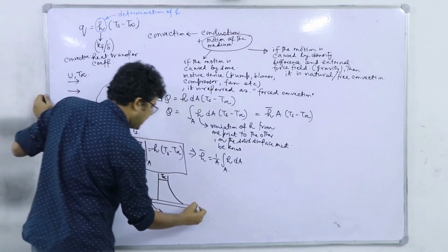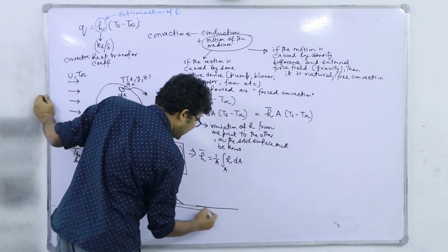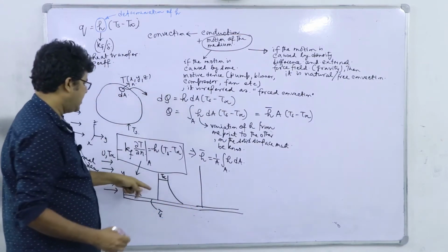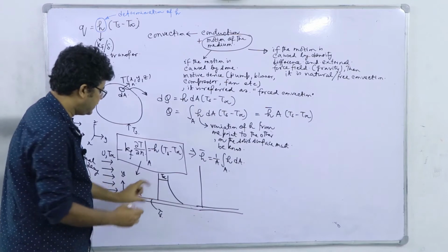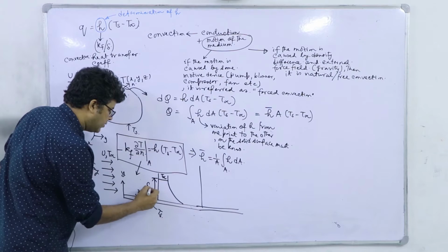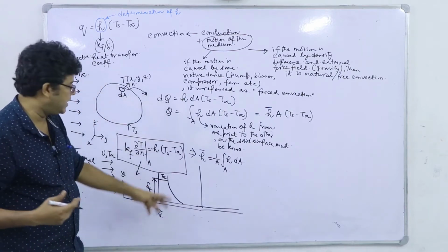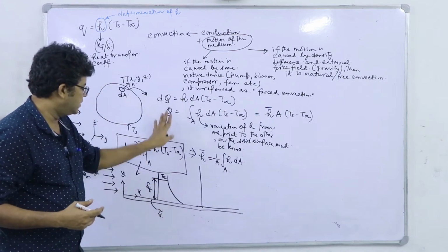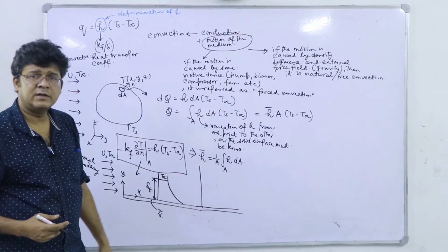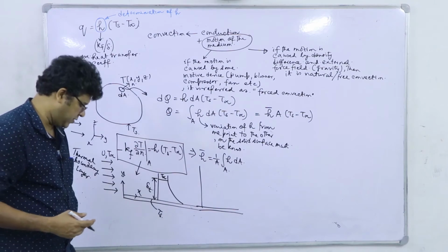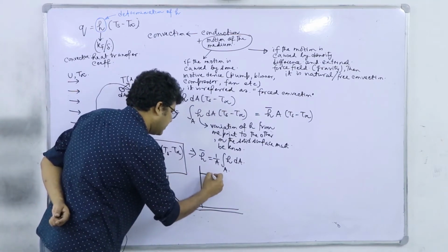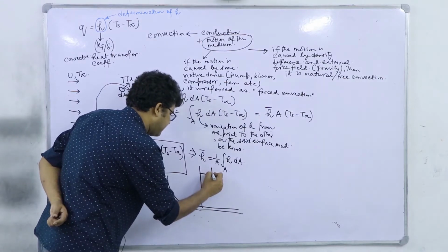And as we go to a higher value of x and draw a similar profile, what is expected? Just like the boundary layer thickness, here it will be delta T, the thermal boundary layer thickness, that will definitely increase because the thermal front will penetrate more and more into that fluid, so this delta value will increase, and it will be something like this.